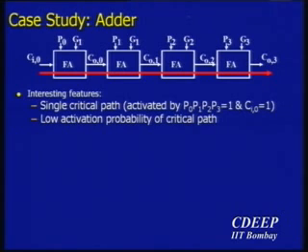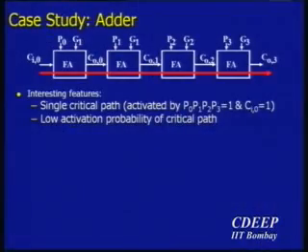So in general, if you look at the probability of carry propagation, that's pretty low, right? But if I look at a few internal bits, it turns out I can do a reasonable job by providing a decoder, and the decoder basically tells me, hey, under these conditions, I'm going to do 2-cycle operations. So bottom line is that I need to come up with a very simple-minded decoder. It can't be expensive in terms of implementation and power consumption and so on. And then, as long as I can ensure low activation probability, I am in good shape, right?